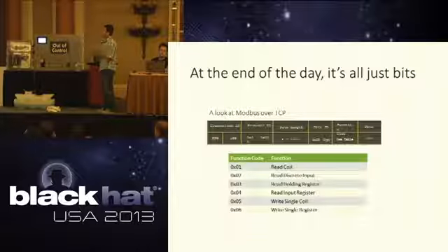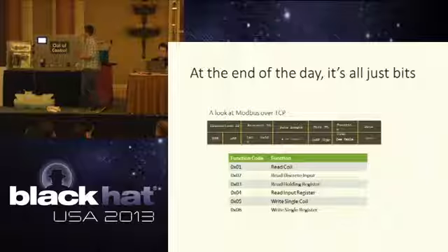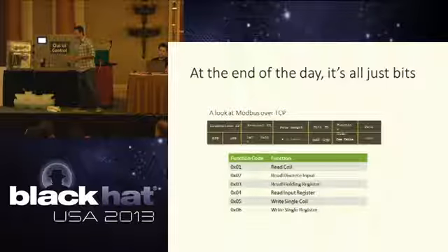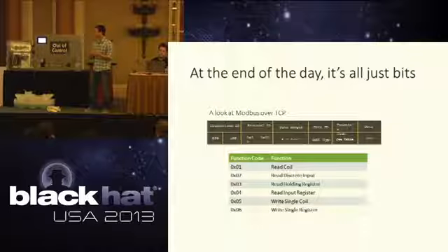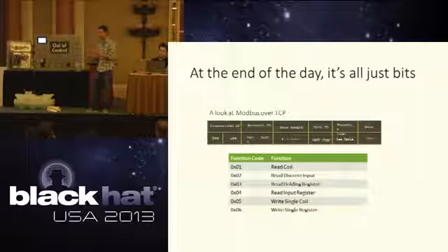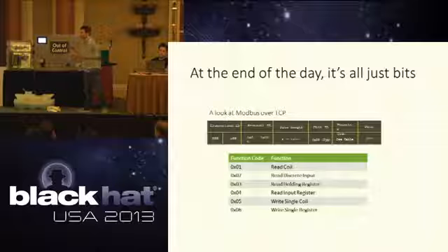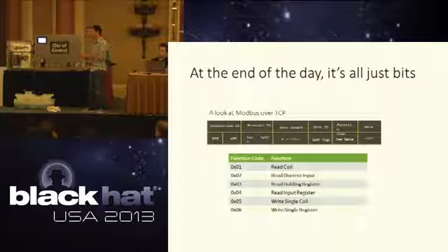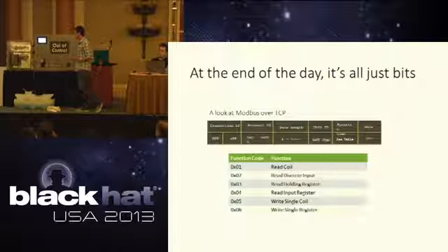So we want to construct a Modbus datagram. So how do we do that? Well, the Modbus datagram is actually extremely easy. It's extremely simple. First, the very first bytes are a transaction ID, and the reason why that's kind of cool is because that's actually a legacy of an older serial protocol. You don't need this transaction ID anymore, right? Because that's handled by higher layer protocols, but they still have it in there to maintain compatibility with the older devices.